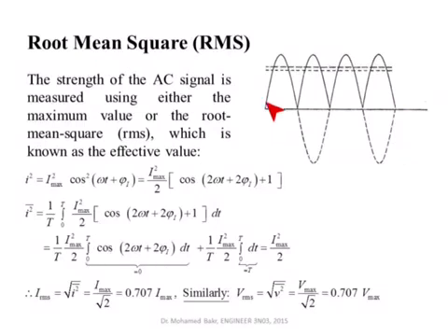First, we square this signal, so when you square it, you get this squared signal. Then we take the average of this squared signal, and then we take the square root of the average. So you can see we do 3 steps. First, we convert it from a sinusoidal signal with 2 polarities to a squared signal with only 1 polarity. So this one here.